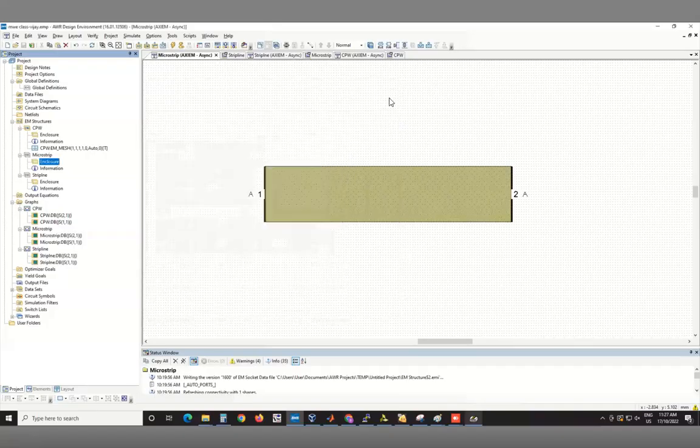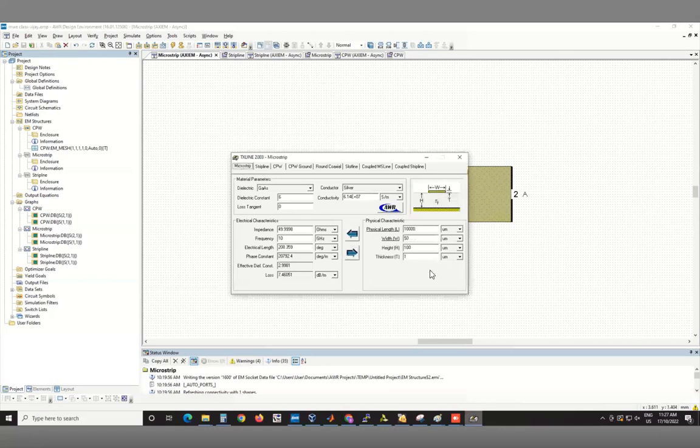Then I've already drawn here a microstrip whose length is about 5 millimeters and the width is about 1.1 millimeters. Let's just go back to TX Line and double check this. So this is 0.762, dielectric constant 6. Set this as 1100 microns. That's basically close to 50 ohms. So this is the right set of parameters.